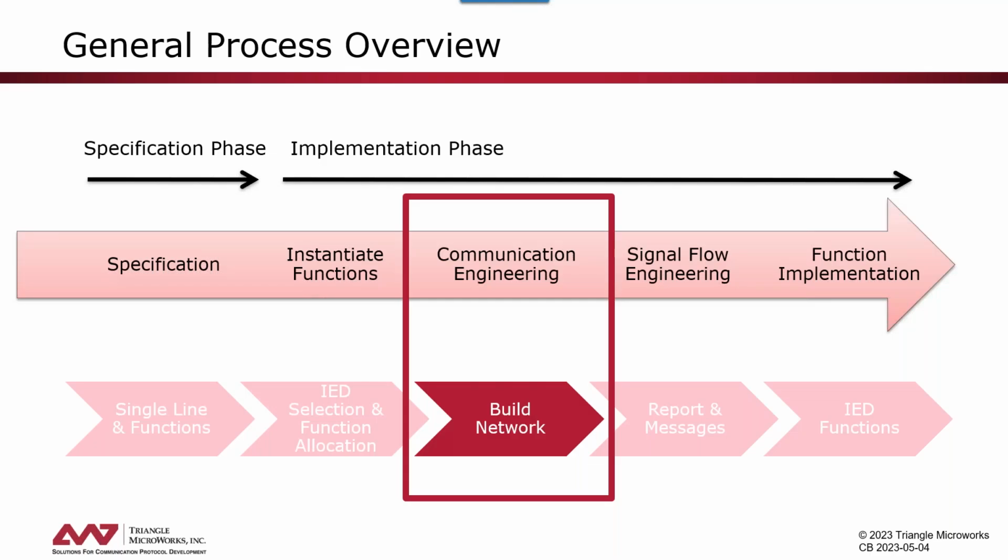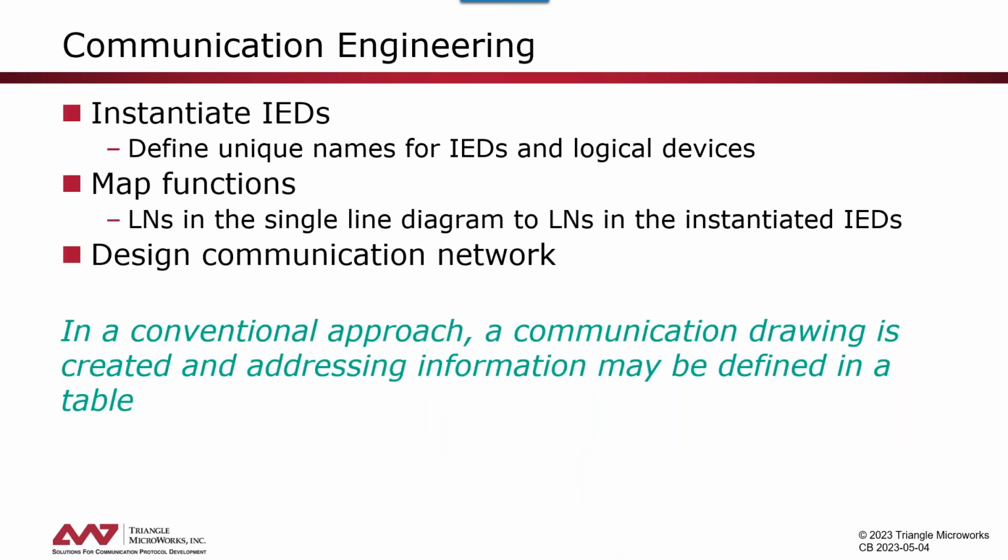Okay, so now we have seen how we create a specification. We have seen what we receive related to the IEDs, and now we can start the process that we do with the system configuration tool, which means import the specification, import the ICD files, and start to do the whole design. When we do a top-down engineering approach, in the first step, we typically start with the communication engineering.